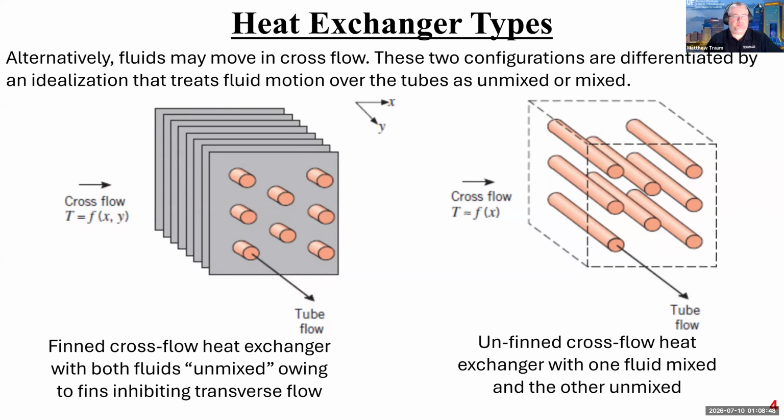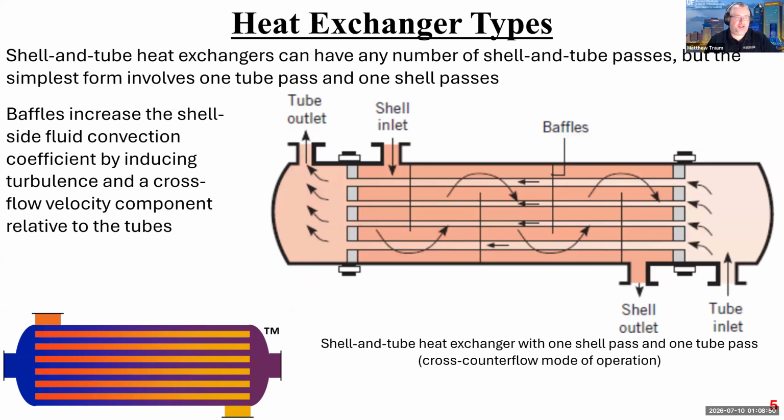Okay. Another very common type of heat exchanger is a shell and tube heat exchanger. These are a broad category that describes all of these different arrangements where we have fluid entering and then passing through tubes, and then having the fluid that enters in the outer skirt pass through the so-called shell. I've got it the wrong way. There we go. Here it is. It's entering here and it's leaving here. And so this is sort of counterflow, right?